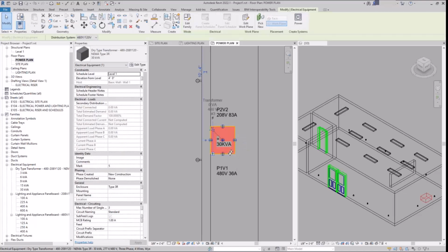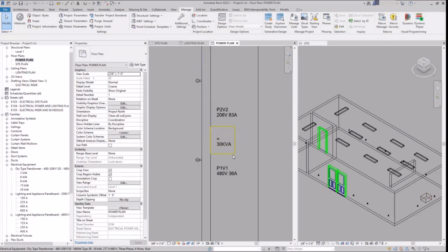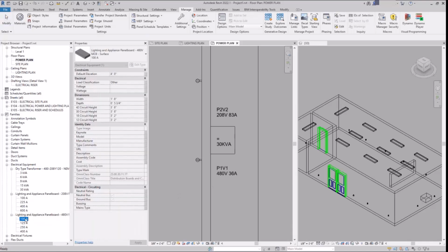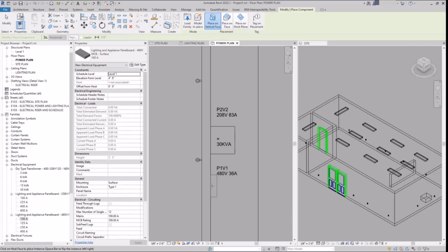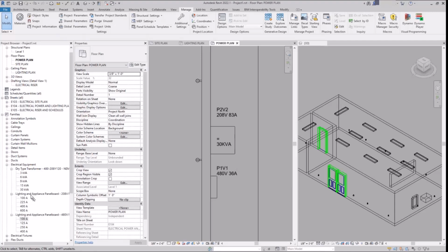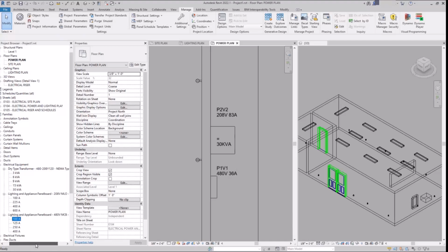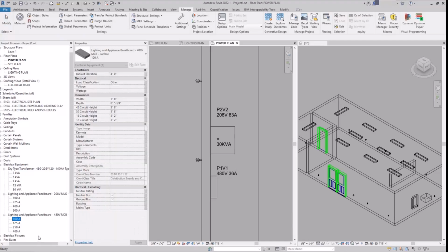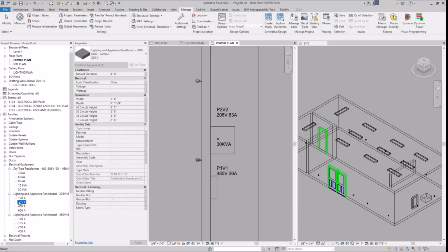You can also think of this as like a pressure reducing valve. What am I reducing my pressure to? What am I reducing my voltage to? All right. So based on that information, on the 480 side, we can use a 100 amp panel board. And on the 208 side, what size panel board do we need? 100, 225, 400, 600. I said 100 amp for the 480. 83, 125. So you're correct. Oh, since this is, sorry, 225. Sorry, I was looking at the wrong one.